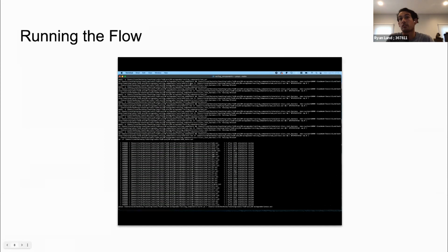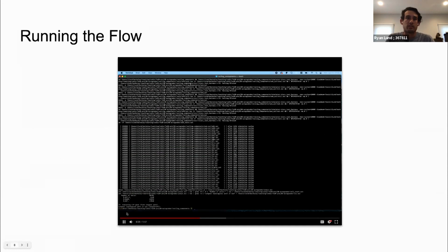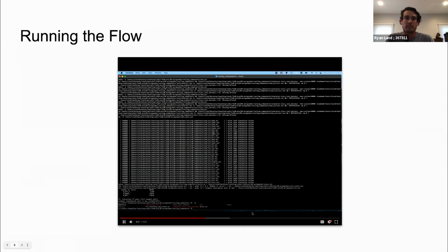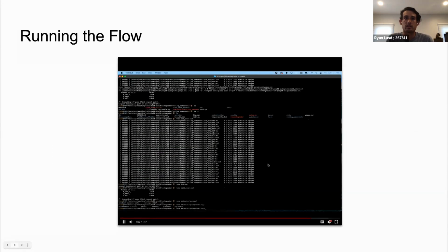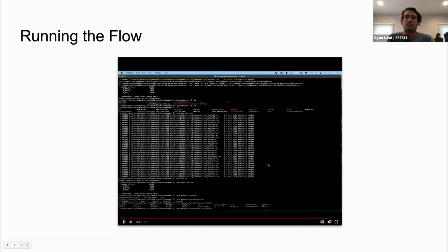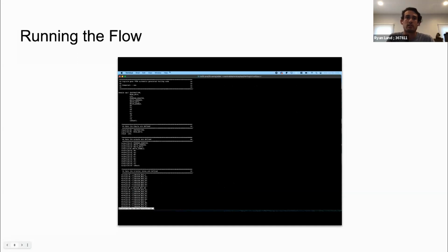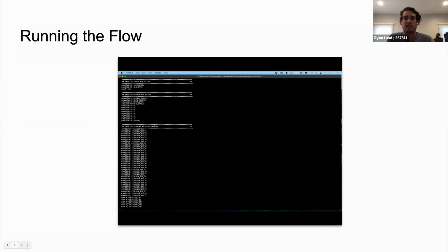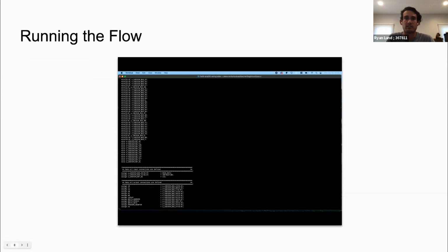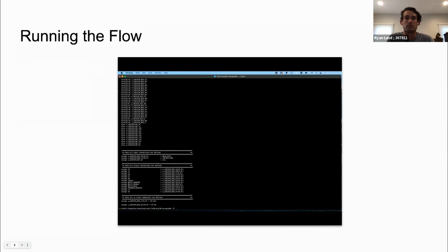Yosys is the longest part of this entire flow, but even then the flow end to end is on the order of a minute or two, which is significantly faster than running Logisim-based tests. So now Yosys is finished and it prints out the different metrics. The rest of this is me just showing the output files. This is some of the Verilog that's emitted. It's very intractable, so it's not really designed to be easily read, but it is a direct correlation to a student's graphical design.